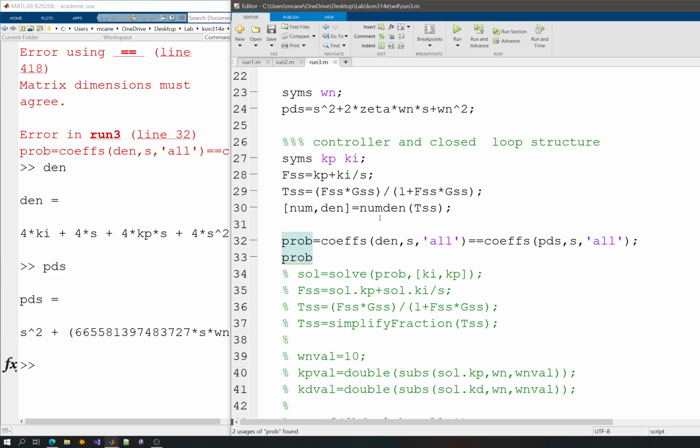And if we somehow can design and assign the poles so that these two pole pairs are the dominant ones and the other ones are not that relevant, they do not contribute to the output, then it is possible to predict what the settling time, overshoot, rise time, delay time properties, or the time domain properties, in other words, are.